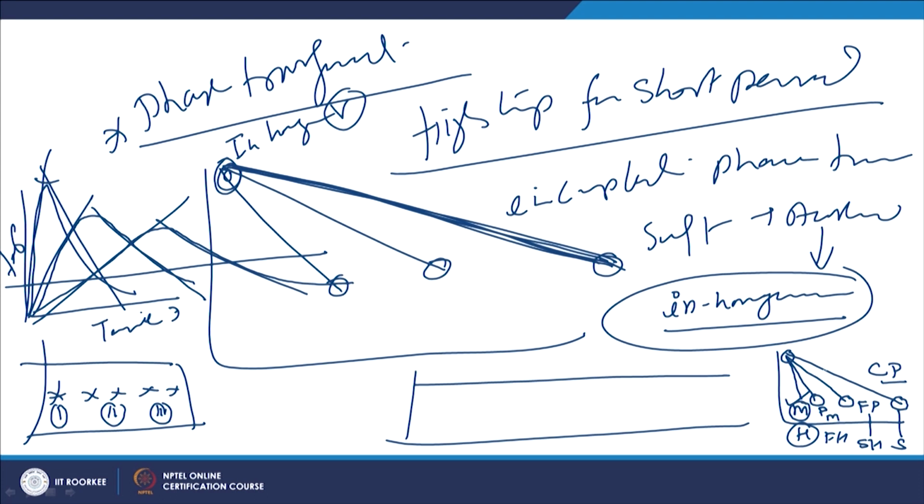It experiences the higher peak temperature, leading to complete homogeneous austenite formation, and subsequently the higher cooling rate leads to complete martensitic transformation.